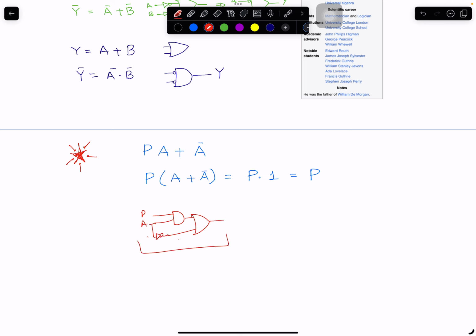This whole thing, you can simply route to the upper. You don't need to waste these two gates. You don't need to waste silicon area with these two gates, which is going to take up area, and also more power. So the key thing is, since A,